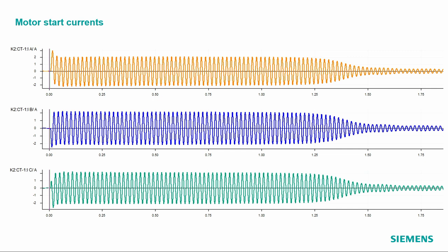So here we see a motor start current, an example, and we see typically three things. The first thing is we have a peak here at the beginning, a kind of inrush current, and then we get the relatively constant current during the startup phase. So this can also moderately slowly change the amplitude. Some low frequency can be also in there, which we don't find in this example here. But basically the amplitude here, the RMS value, is more or less constant. It can also decrease slightly.